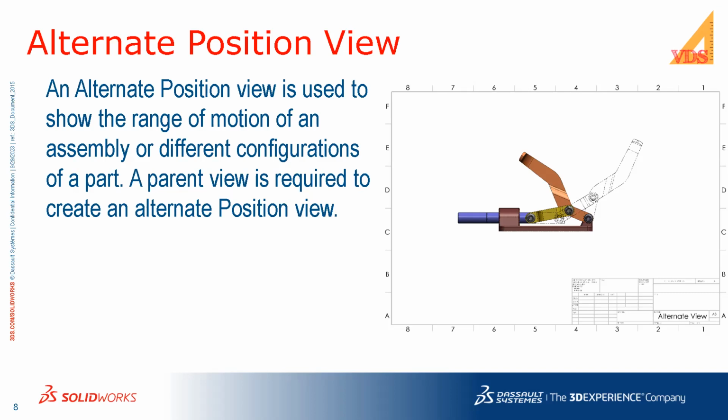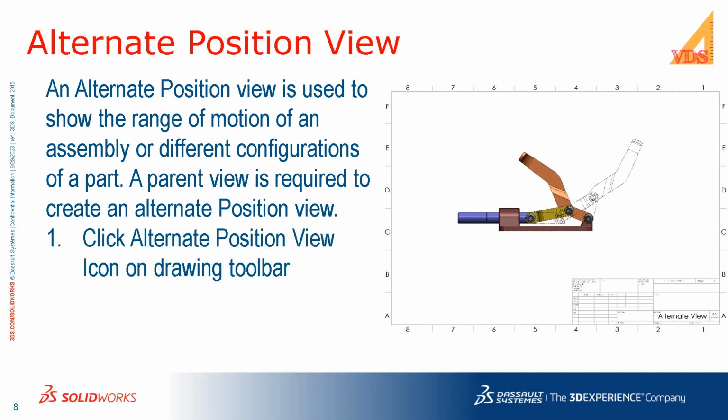They want to show the cast part and the machined part in the same view, so that the shop floor person will understand that this is the finished part, and the dotted line shows that there will be extra material outside the machining area. So this view is very helpful, I would say.